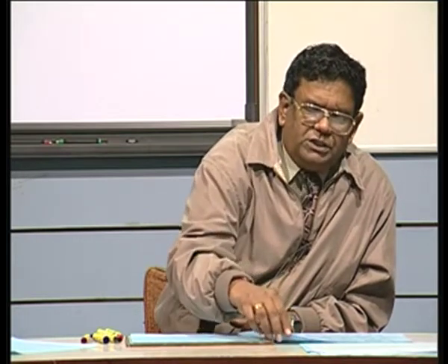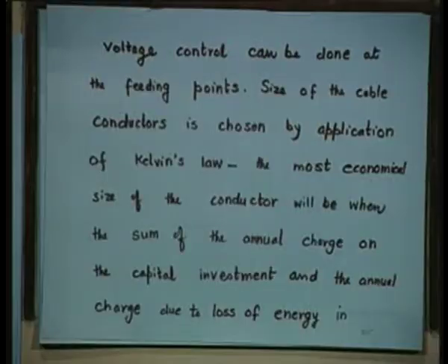How do you do voltage control at feeding points? Same methods. You have to have capacitors, inductors, or SVS, or FACTS. There is a big family of FACTS now. There are books available on FACTS. The recent book is by Mathur and Verma, a very good book on FACTS devices. Both are Indians, both settled in Canada.